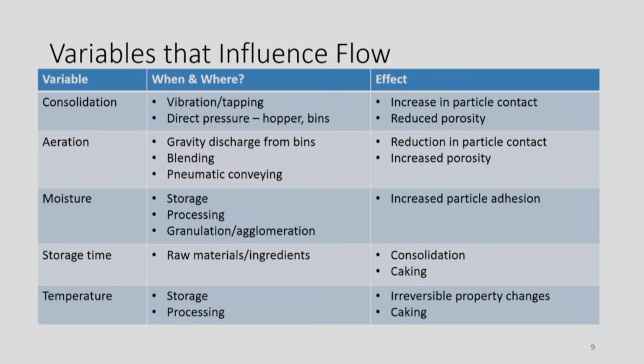Storage time, again, if you are storing powders for a longer time, it keeps on consolidating, right? From its own weight, it consolidates and then starts caking, right? Then it doesn't flow. And if you're putting material that can cake in large silos, then the silos can fail or break. And again, temperature leads to irreversible property changes, caking, etc.